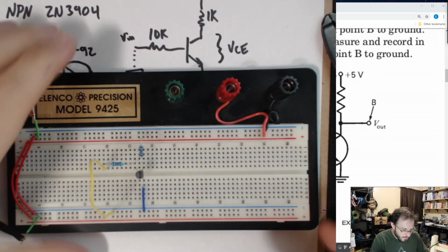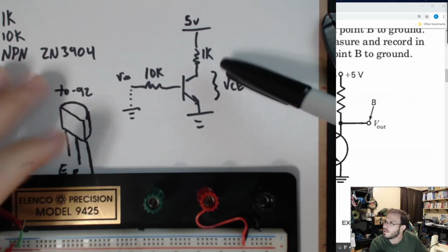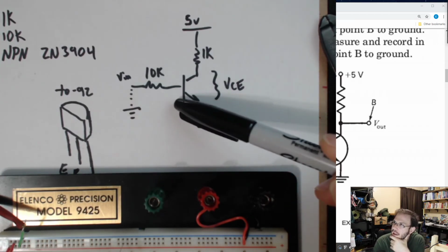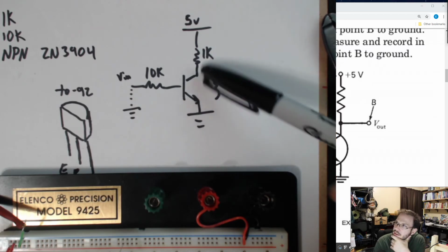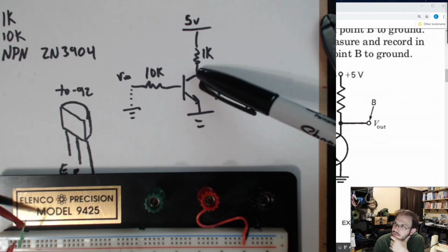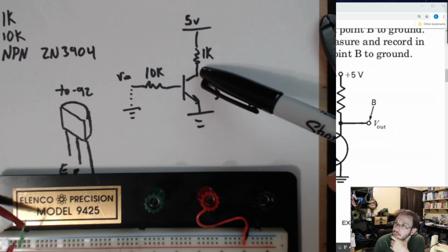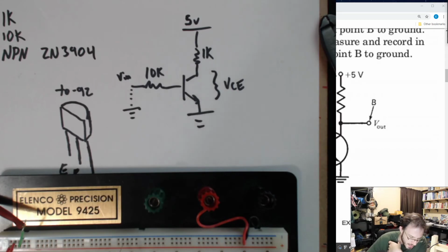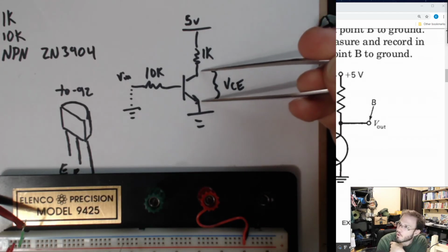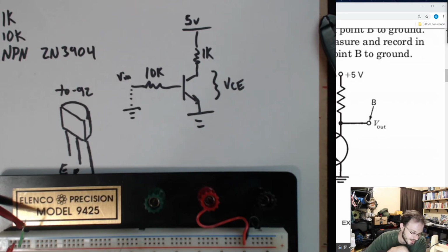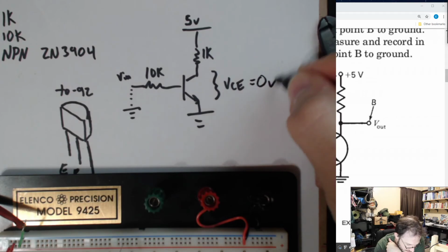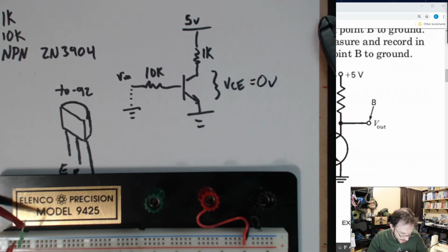So you think it should be 5 volts. And I'm assuming with this tied to 0, then we have 0 for the base current. If we have 0 base current, this transistor should be in cutoff. If this is in cutoff, then it is open between these 2 points. We have no current flowing through this 1K, therefore no voltage drop, so we should be measuring the entire 5 volts between these 2 points. That is the prediction given by, was that Justin? Yes, sir. Sweet, thank you.